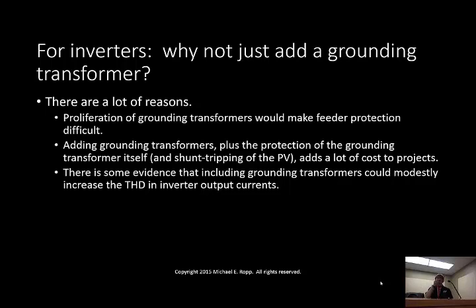Last but not least, there is some evidence that if you hard ground the neutral point on an inverter, that actually causes some increase in the output distortion. And the reason appears to be because if you don't ground, the neutral wiggles around a little bit as each of the 3 phase legs is doing its switching thing. If you fix that point, now those wiggles are going to be reflected out to the phases. So there is some degradation in inverter performance that could be expected if you hard ground that neutral point.